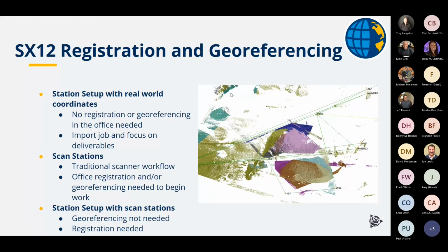Okay, the scan stations. I like to use those as a supplemental, and we'll see this here in a minute. Let's say you're set up on point A, backside point B again, and then you do a scan, and then maybe you shoot your foresight in, which would be point C, and then you're going to move, let's say, 200 feet, but maybe at 100 feet you need to capture some information.